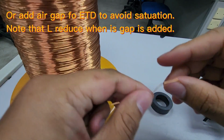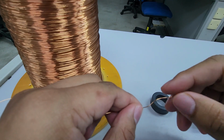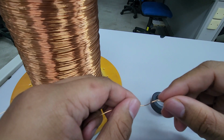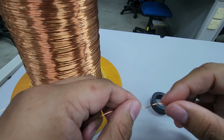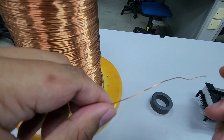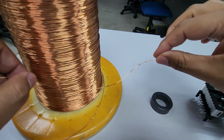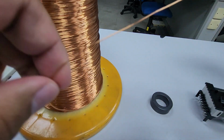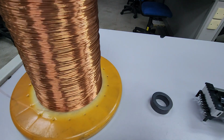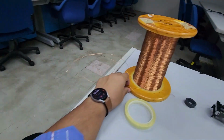So like I showed before, you are doing maybe a small one, and maybe the current is 3 ampere. This one, like I said before, is 1.5 ampere only for 0.6 mm. So it should be 2 wires parallel to each other. The length should be calculated, but because we are using the trial and error method, we just estimate. How many is 19 windings? You have to estimate it properly. I think this should be enough.